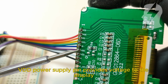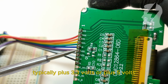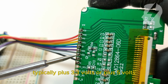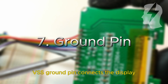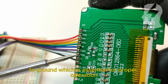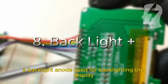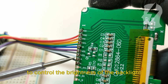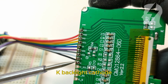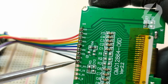VDD, power supply pin. Provides voltage to the display, typically plus 3.3 volts or plus 5 volts. VSS, ground pin. Connects the display to ground, which is essential for proper operation. A, backlight anode. Used for backlighting the display. Connects to the power supply through a resistor to control the brightness of the backlight. K, backlight cathode. Responsible for connecting the ground for the backlight.